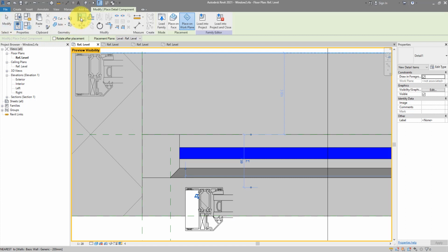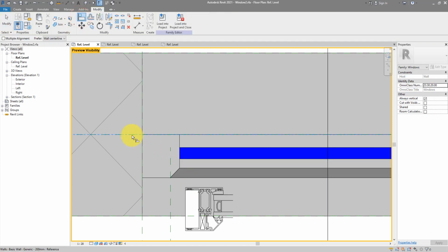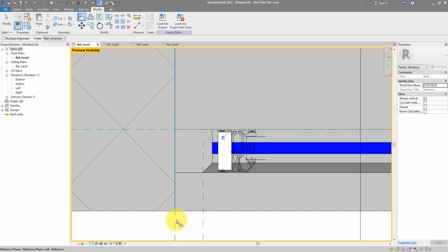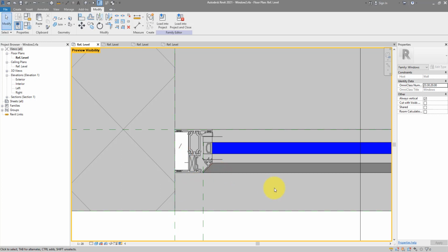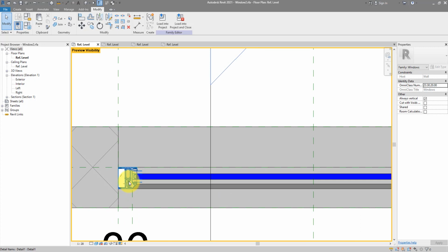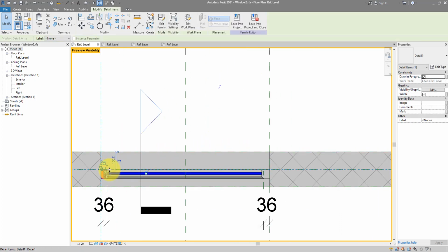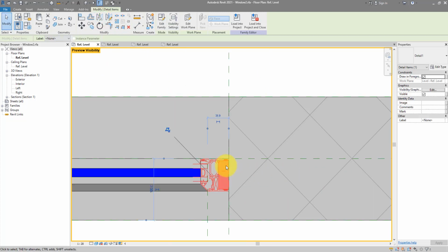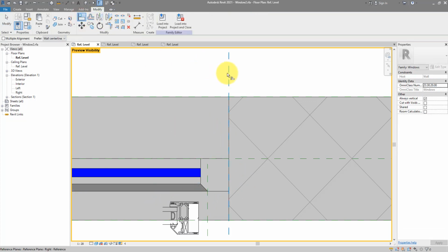And now it's time for me to do the align command and just align it to the right position. So from this plane there to here. Lock it. From this other plane there to here. Lock it. Let's do the same profile but on the other side. I can quickly mirror this one there to make the second one. So select there, go to mirror and then pick this center plane. Now it may be looking to be at the right location, but there's no constraint setup for it yet. So we can now repeat the same process. I will bring this a bit off to the side and do the alignment twice again.